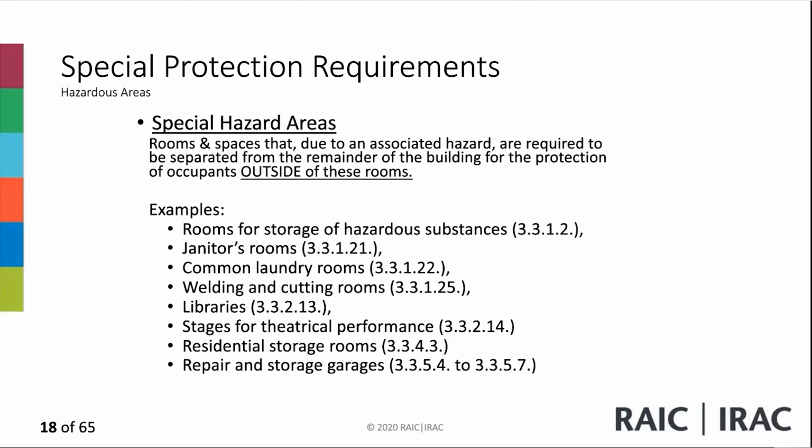Another allowance tells me the fire resistance rating of the fire separation required by sentence 1 is permitted to be less than 1 hour, but not less than 45 minutes, if the fire resistance required by subsection 3.2.2 is permitted to be less than 1 hour.